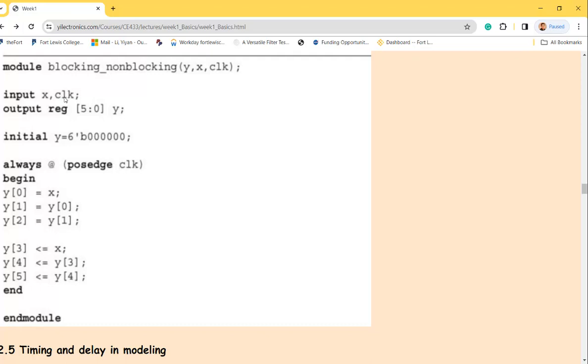you just give x to 1 here, and then you repeat for 4 times. It could be 3 times, doesn't matter. It should be for 4 times. You add a time delay here first, like 20 nanoseconds, followed by flipping clock. Just use this one for the test bench.